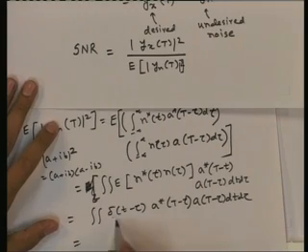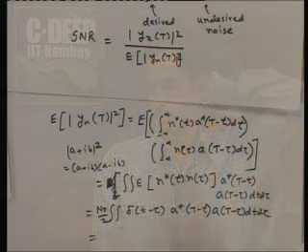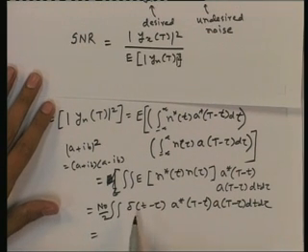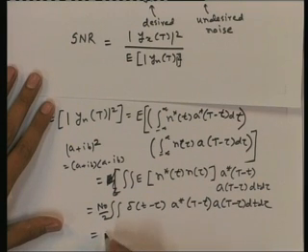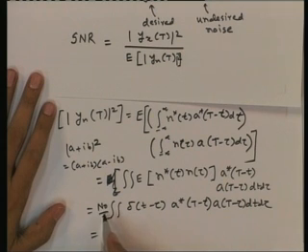This is equal to, now this is N0 by 2, because noise is assumed to have, suppose, N0 by 2 variance, that is the two-sided power spectral density. Then this expectation is delta(t minus tau) N0 by 2. At t equal to tau it is N0 by 2 delta, and at other places it is 0. So this at t equal to tau it is infinity, but other places it is 0. The variance is N0 by 2.